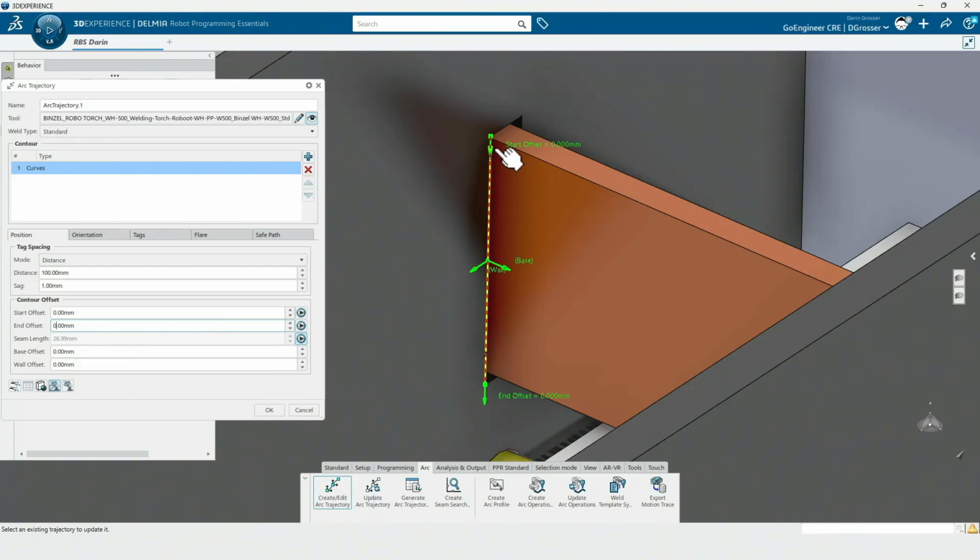So if you need to change the direction of an offset, for example, we select it, and it simply changes the end to the start and the start to the end and vice versa. That's nice to do after you've run a quick test, and there are collisions involved, and maybe we have to approach it from a different spot or a different angle. Now, in some cases, you can drag those off the edge. I have these as driven ends, and I can only drag the one end since the other happens to be driven.